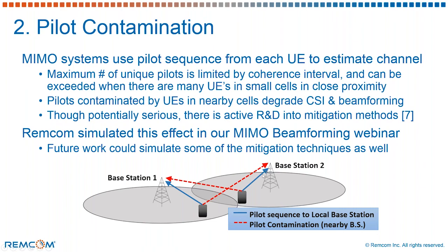Research suggests that with at least 10 times as many antennas as users, the channel conditions are reasonably favorable that the MIMO techniques can be successful. So this particular one doesn't appear to be an issue for the planned deployments of 5G FD-MIMO, which are planning to include large numbers of antennas and supporting perhaps 8 or 10 users at a time.